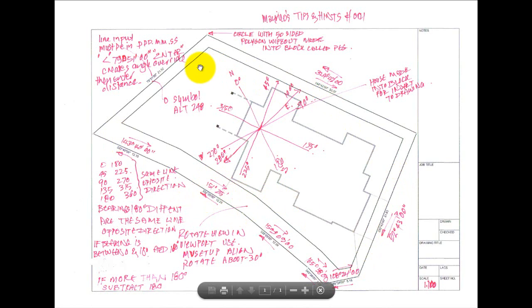And I've done that for most of them here, all of them except this one. So that's your bearings. You have to get them going in the right direction, which you can work out from this diagram. So if, say for instance, this bearing here, which might have been 259.51, was going that way and I want to go the other way, I just subtracted 180.